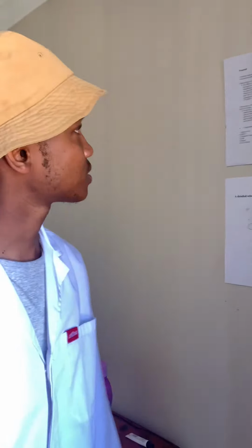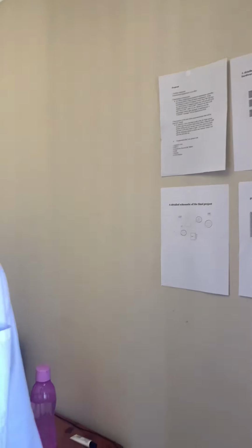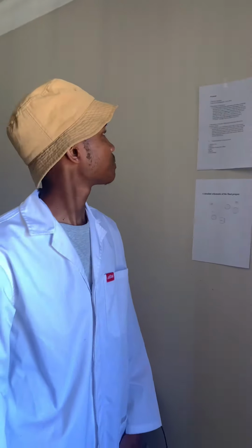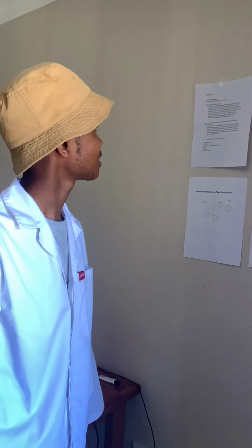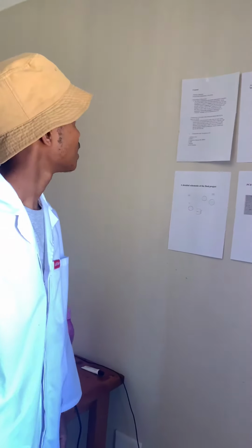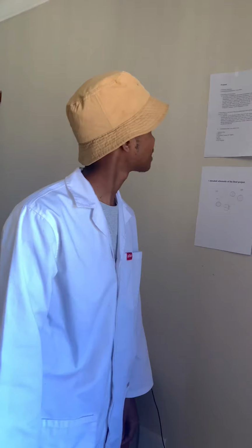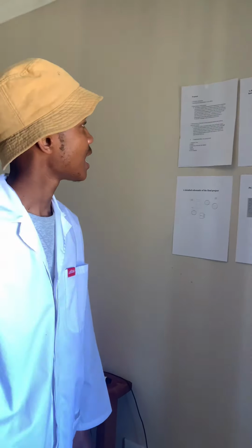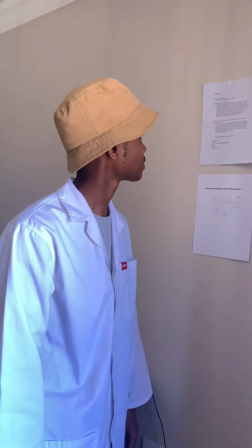First of all, I would like to start with my proposal, with the problem statement. The problem statement here is unmonitored temperature in an office. The description of my project is an office containing an automated temperature controller having the DHT11 that will detect temperature. If the temperature is above 27 degrees, the fan will turn on and the LCD will display that the fan is on. And if the temperature is below 27 degrees, my fan should turn off and the LCD should display that the fan is off.